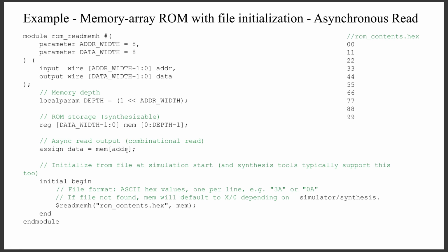Alright, asynchronous read output, we do a combinational read and initialize from file at simulation start. So we read from ROM contents.hex into memory.